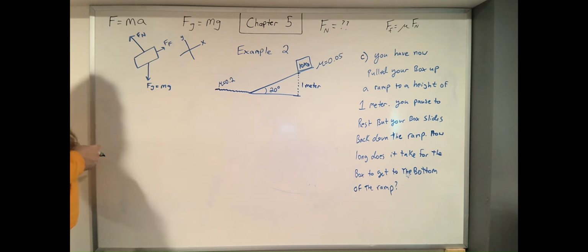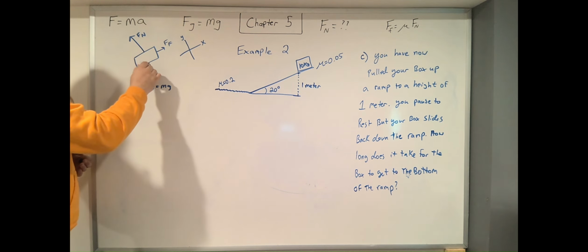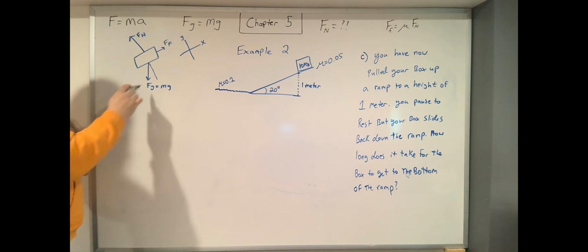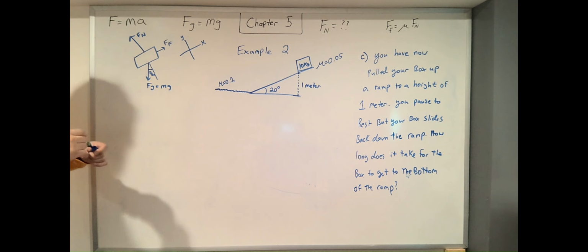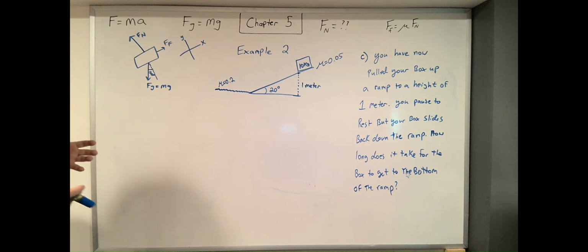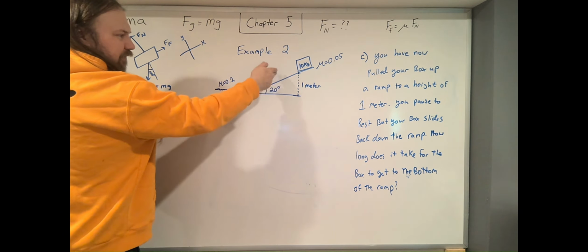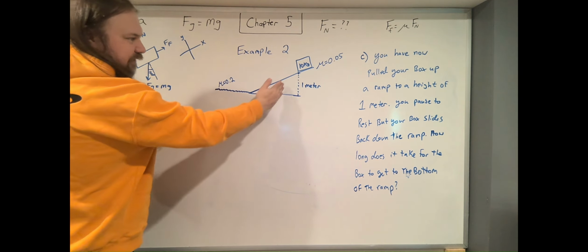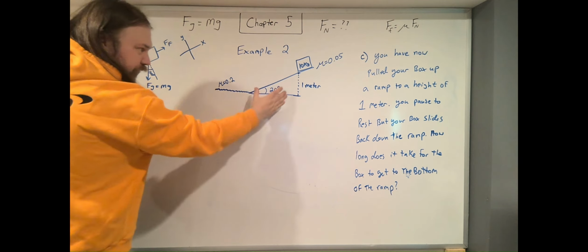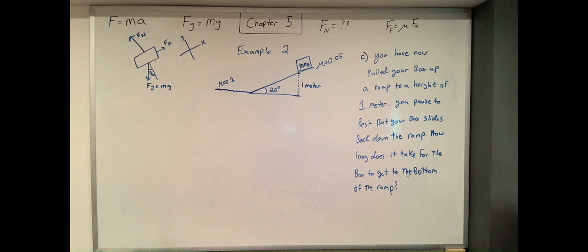Okay, so which means I'll need to break that gravitational force down. Well, what's the angle on the gravitational force? Okay, some simple mathematics here. If this was coming straight down, this angle here is that same 20-degree angle that we're seeing over there. If you need to convince yourself of that, imagine having the block on there, and the gravitational force coming straight down. Then rotate that block 20 degrees. You'll see that the gravitational force will then also come over 20 degrees. And that's how we're getting that 20-degree angle in there. So hopefully that makes okay sense.